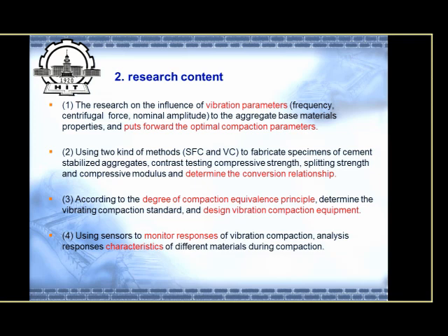Then use two kinds of methods to fabricate specimens of the same stabilized material and do contrast tests, and put forward the conversion relationship of the two methods. According to the degree of compaction equivalence principle, we put forward the determination of the vibrating compaction standard and design the equipment.